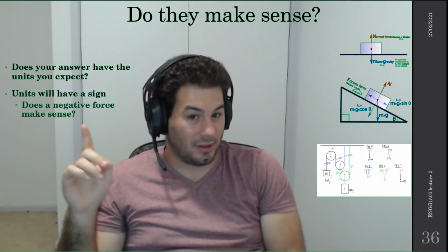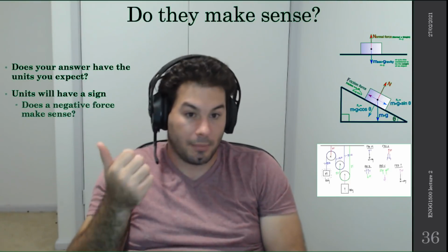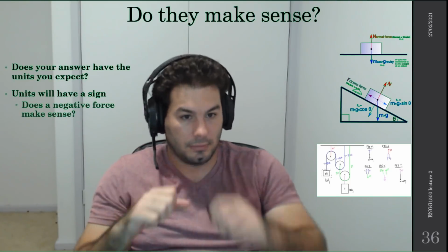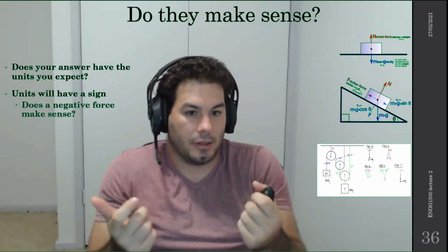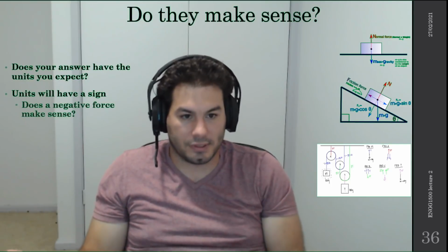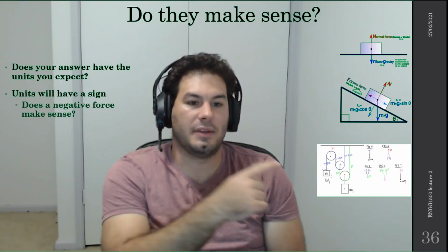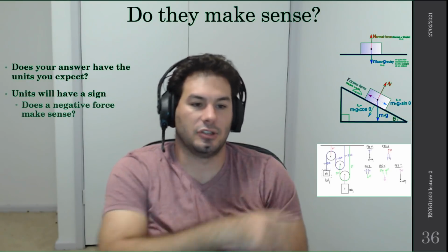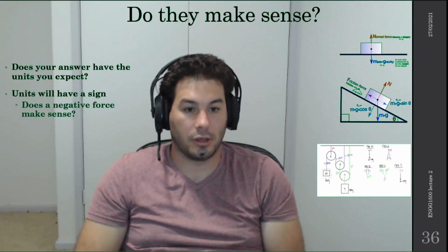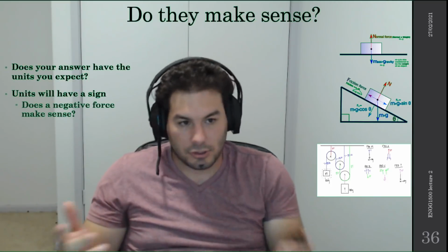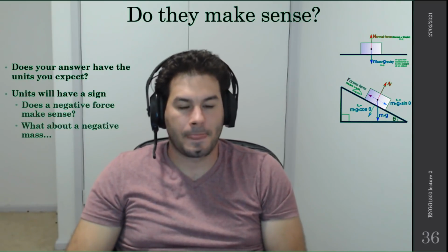Also, disclaimer, ropes, pulleys, I can put rope into tension, right? Very strong. What happens if I put rope into compression? Doesn't do anything. Ropes don't transmit force in compression. So tracking this type of thing, being very careful, realizing at some stage in your system that you would need a rope to be in compression for it to work, means it doesn't work. So really useful stuff that you can derive from your systems.